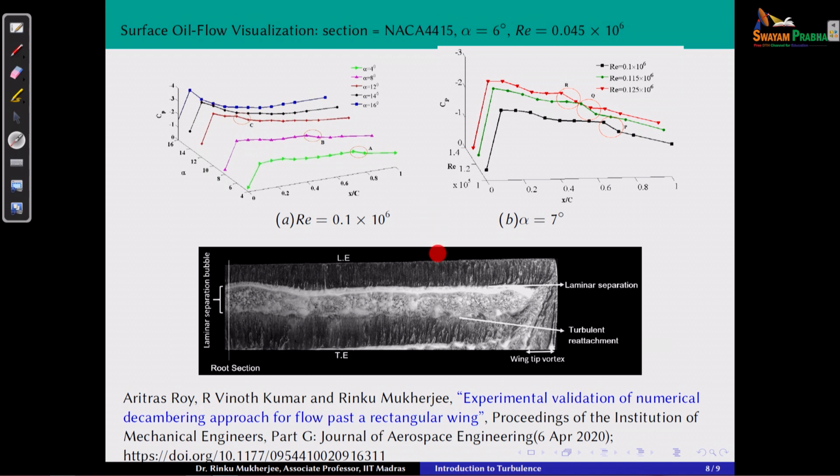So the flow comes in here, pushes the oil along this edge, right, from the leading edge to the trailing edge. So it pushes the oil in this direction, which is the chord direction, and then again it leaves it. The flow is now leaving the surface. It's not doing anything to the oil, and again it touches back and forces it out. So therefore we think that this is a laminar separation. The moment separation happens, it has to be turbulent.